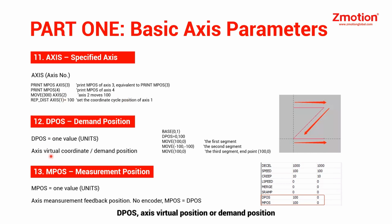DPOS, axis virtual position or demand position, is used to see the running situation. When the DPOS value is modified, the motor will not move. MPOS, axis measurement position, is used to see the encoder feedback position. When there is no encoder connected, MPOS equals DPOS.